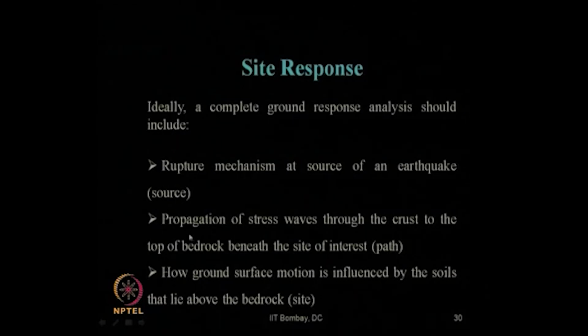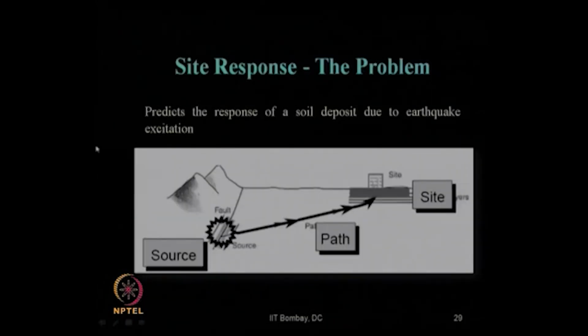Next is the propagation of the stress waves through the crust to the top of the bedrock beneath the site of interest, which we call the path. And next is how the ground surface motion is influenced by the soils that lie above the bedrock, which we call the site. That means, if we go back to the previous picture, this is the first one,